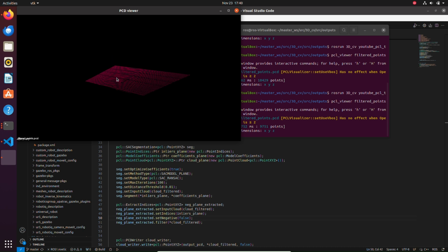For example, if you need to run inside a robotic application where you need to dispense glue inside a plane. Usually in industrial applications you dispense the glue on the edge of a plane, and you need to sense the plane right. Then you can use the Point Cloud Library plane segmentation, and set negative to false, and here you have your plane, and then you can get the coefficients of the plane.